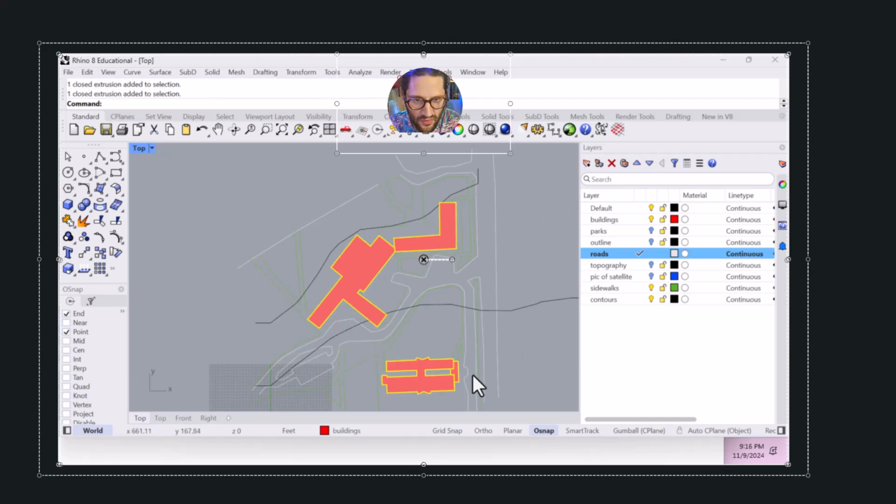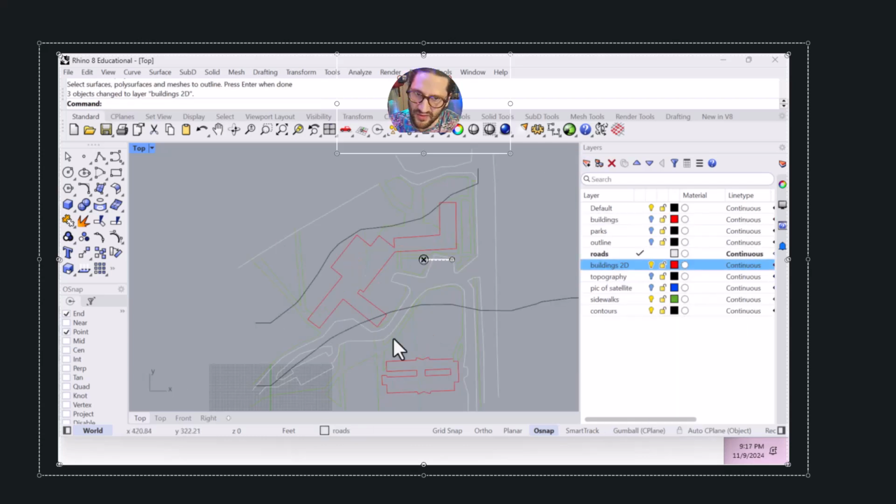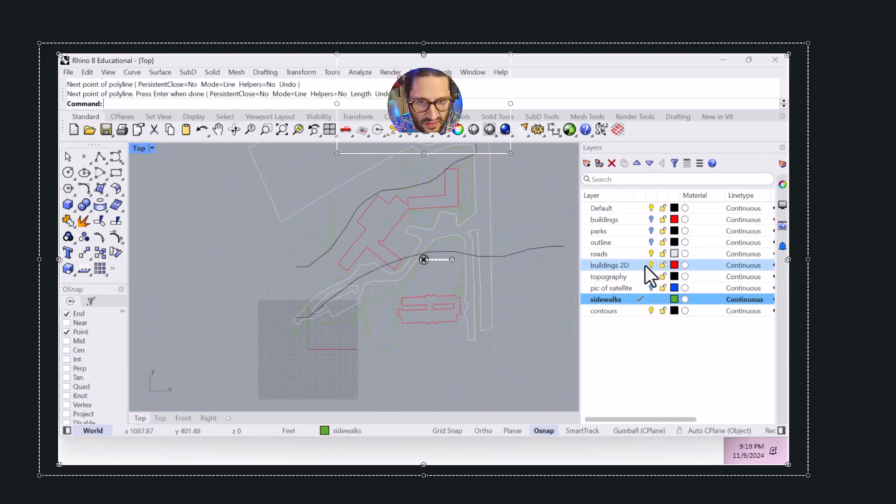And then what do I do? I select the buildings themselves and I just do a mesh outline. That's a really handy dandy feature in Rhino, mesh outline. It only works on mesh, but you select 3D objects in whatever view you are. It's like a make 2D, but it's just the outline. It's real handy dandy, and I got that. And then I was just trimming little lines here and there.